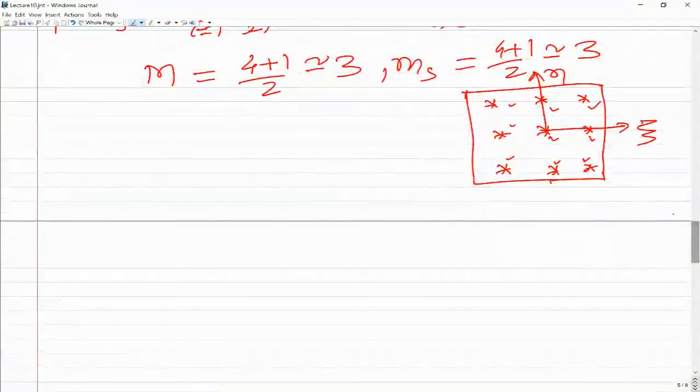Now one of the important things is knowing the shear deformable plate element. We have discussed classical plate bending elements, and we have discussed first order shear deformable plate theory based elements. Now the problem is, suppose we use these shear deformable elements for solving thin plate problems, where a is much larger than thickness, a by h greater than say 30, so it would be a thin plate. There is a problem called shear locking.